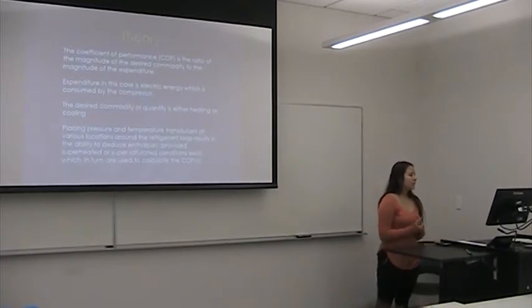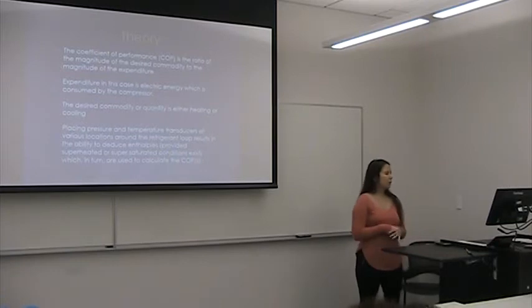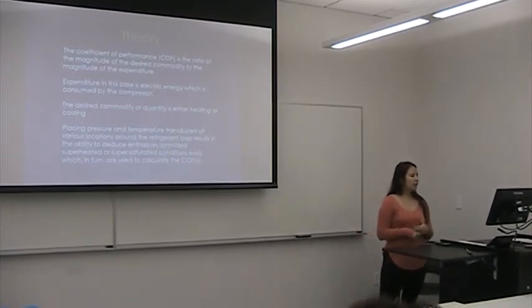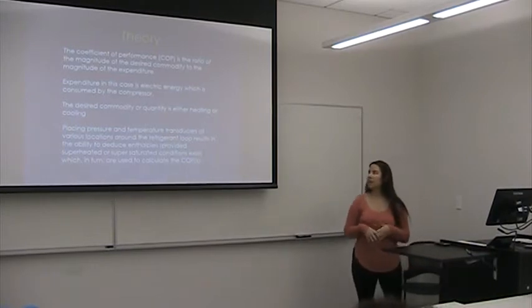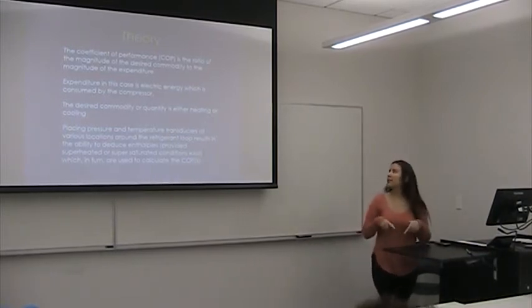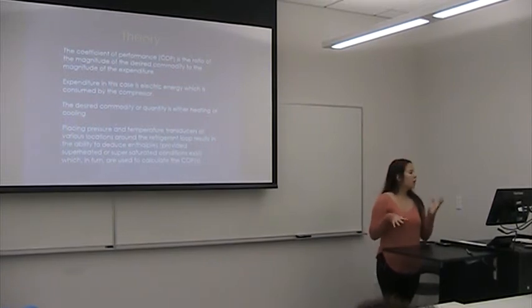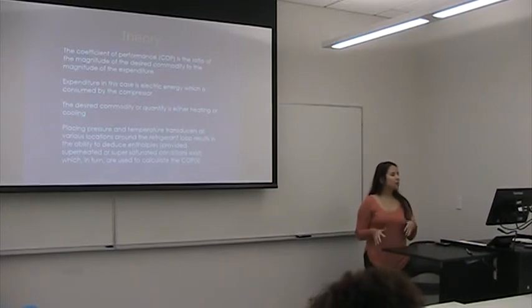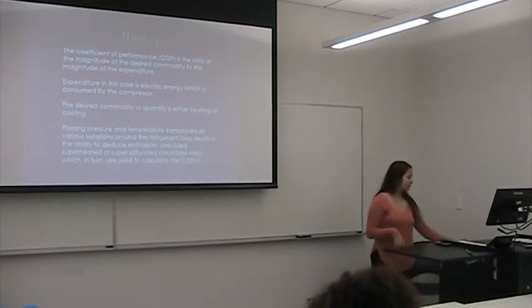The theory. The COP is the coefficient of performance, which is the ratio of the magnitude of the desired commodity to the magnitude of the expenditure. The expenditure in this case is the electric energy or power which is consumed by the compressor. And the desired commodity or quantity is either heating or cooling.